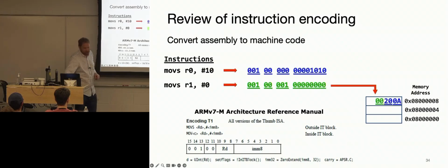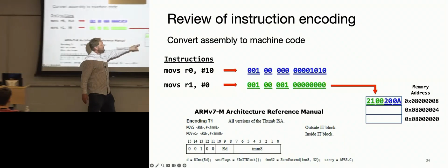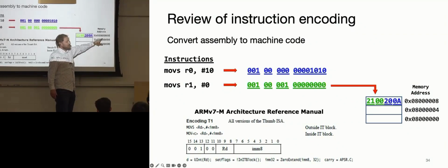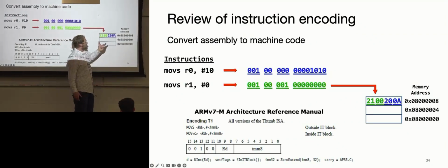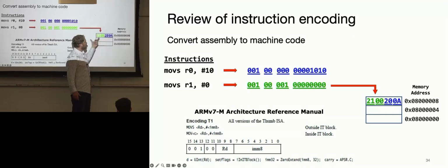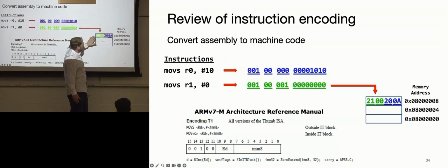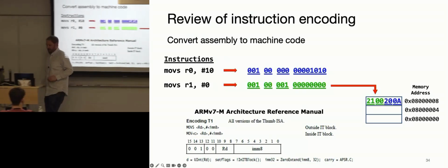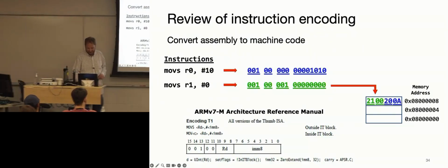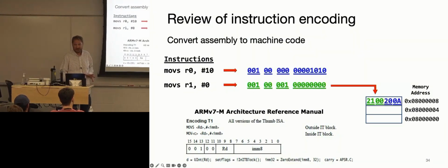I can store that in the same memory address, right? So remember, these are going by 4. This is a world where you can store in bytes, half words, and words. To save space, you could have made this all zeros, that would have been fine, but to save space, we're going to put 2 instructions in one 32-bit memory location. How do you feel about that?